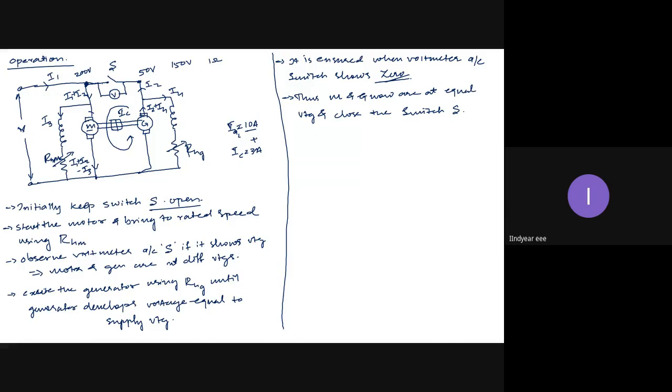This 3 amperes of circulating current is very hard to measure. I cannot measure that. It is difficult to measure. Okay. Now, if you load the machines up to their rated currents, then additional circulating current is also flowing. So even when the motor is at its full load, it is always overloaded, both the machines. To avoid that, what should I do? The maximum current carried by the armature should be only 10 amperes. Then I have to load the machine only up to IA equals 7 amperes.